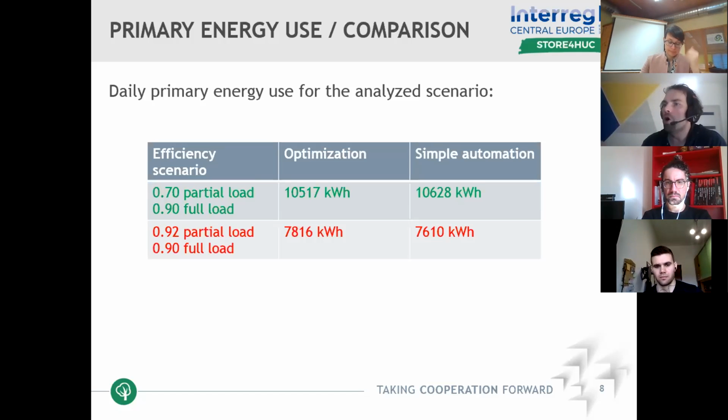Basically, you don't get benefit from just engaging your heat source more and tripping with temperature to higher values for a while, because simply you don't run on higher efficiency. And in that case, it's good enough to just have a simple automation and fully rely on it and keep the temperature all the time at 80 degrees, or maybe if some other reference temperature is required, the automation can give you the correct amount of power to achieve it.